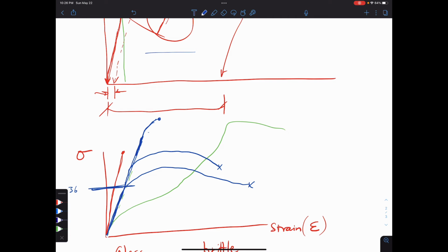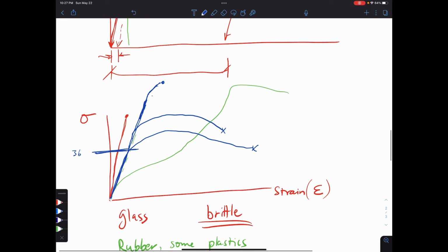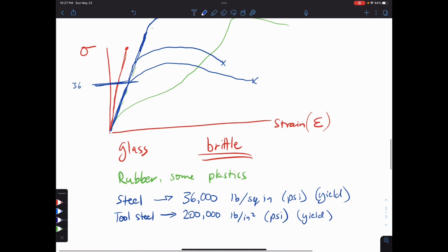So steel varies in strength dramatically, and it really depends on the alloying of the steel, the little bits of other materials you put in, like vanadium and nickel and moly, chromium. There's a bunch of different metals that you can alloy into the steel, and they all have different effects in terms of how hard you can get the steel to be and how much strain it has, how brittle it is, etc. And so we use different steels for different things.